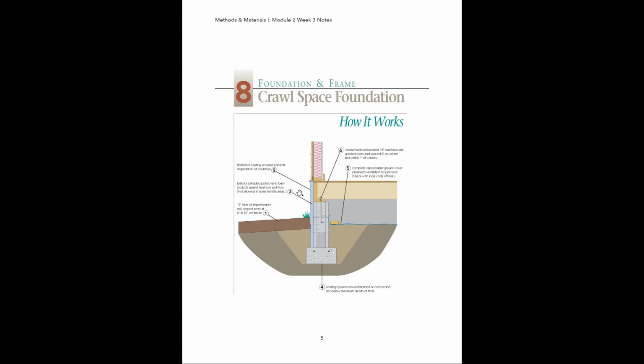All right. You can see here's the foundation wall. That is made up of CMU in this case. So CMU, concrete masonry units. These are basically concrete blocks that are stacked on top of each other. And they only go a little bit of the way up above the soil. And then your superstructure sits on top of that, and basically everything else is built up from there.